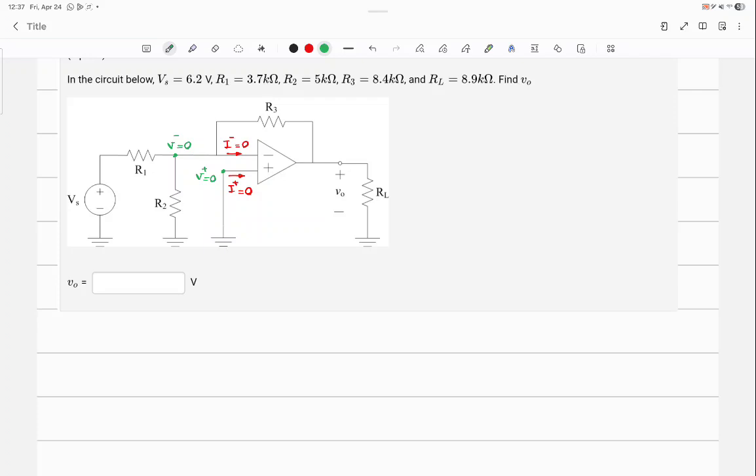Yes. You just follow it all the way over, when it beats 0 again, because there's no current, so going through R3 is 0 volts, going over to VO, you have 0 volts. Okay, you said there is no current going to R3? What it looks like. Why? You have 0 current going there. There's a voltage source. It's not a current source, but there's a source. Wouldn't it go straight to the ground? Well, no, it is parallel with resistors, it isn't just a wire.